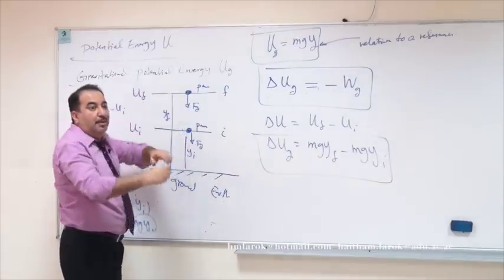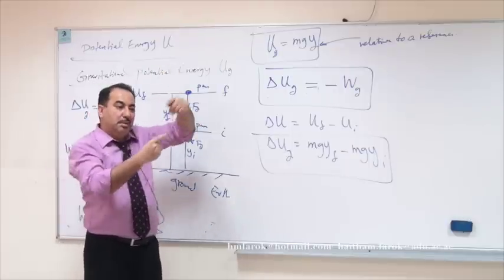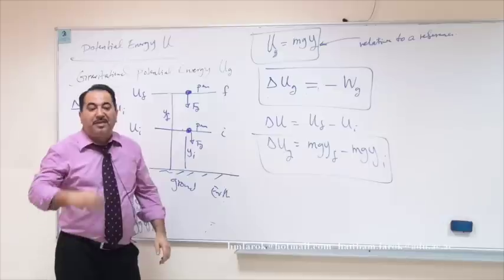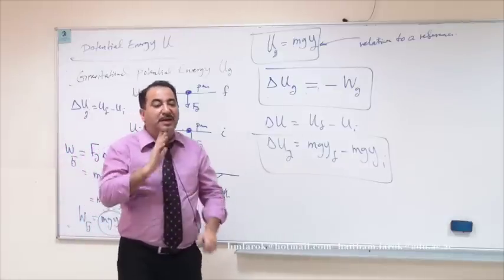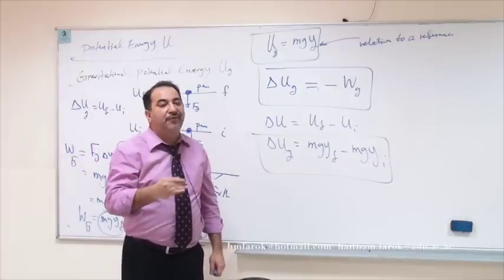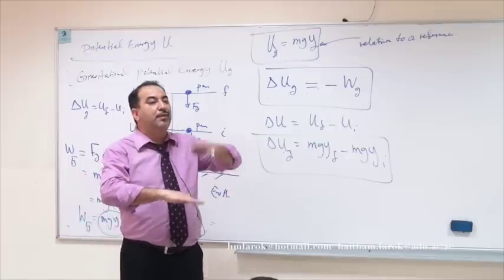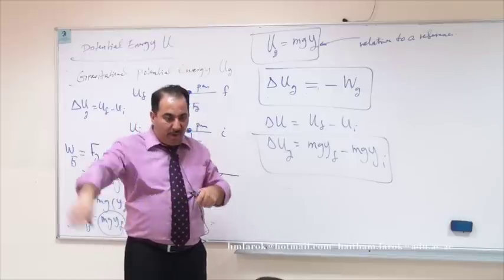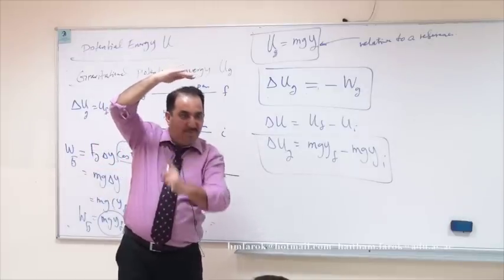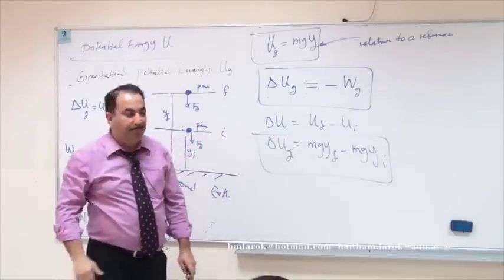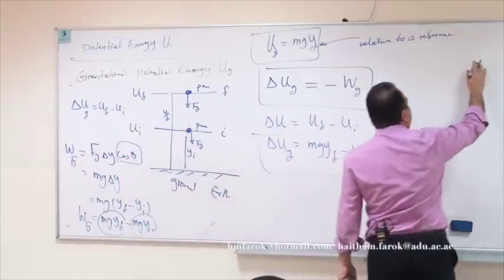Like the ruler, where you put the 0, then you measure from the 0, yeah? But the best way is this. This is very important. The best way is to always put the reference at the lowest point. Why? Because then you have every y positive. If you have the reference above, you'll have negative y's. Okay?